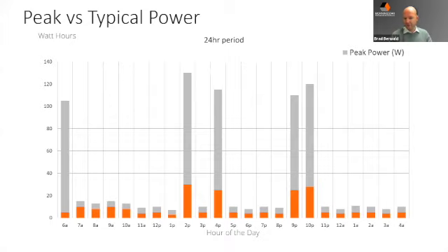But if you were to actually graph the peak power draw, and if you didn't have the sort of resolution that you'd want to have with these sites, you may miss that even though your power draw is overall on average pretty low, you have some pretty high peak periods. And if those loads actually draw too much power, more than you're counting on, because they're not really running but just a few times a day, such as pumps or heavy equipment, then you might not get the full picture. This is nice because when you have the ability to measure load current, you not only get throughput and amp hours, but you also can see your maximum current draw. And sometimes that can be pretty substantial.